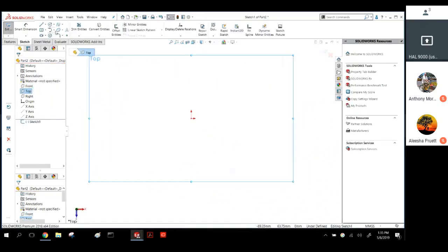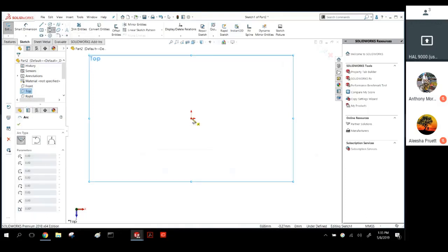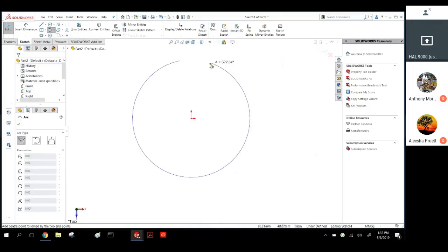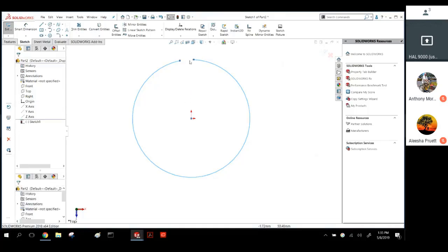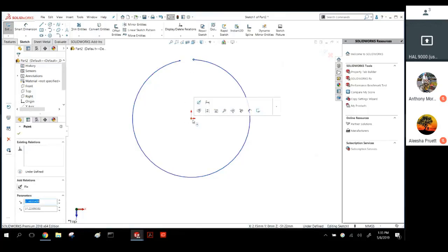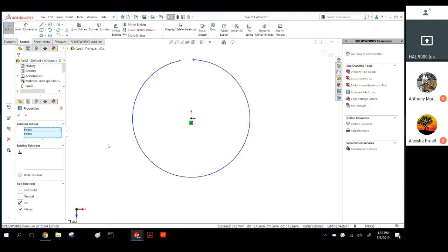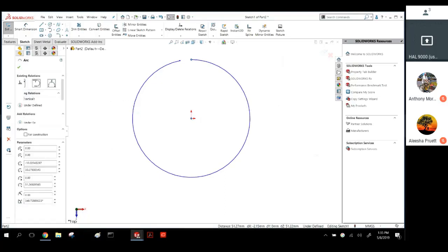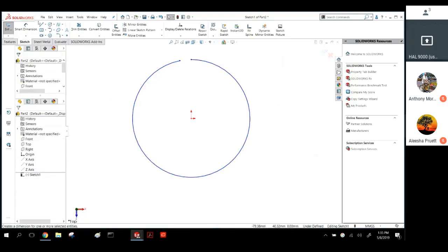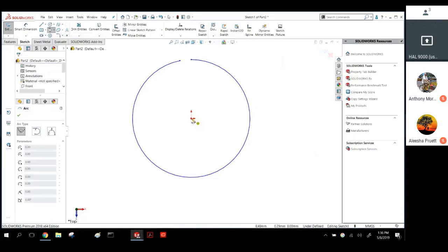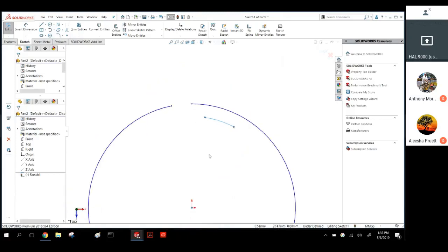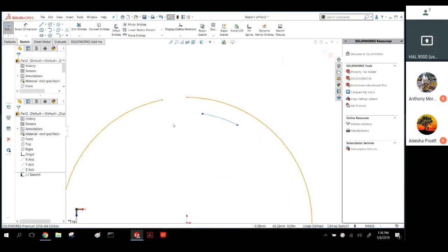When you're doing the math for a press brake, as far as the flat pattern, the mathematics is much more straightforward. You're always going to get the same amount of stretch every time you bend this thing if you're using the same machine. When you're doing a roller, it depends on how much the guy bears down on it, really, for the amount of stretch that you're going to have on that.